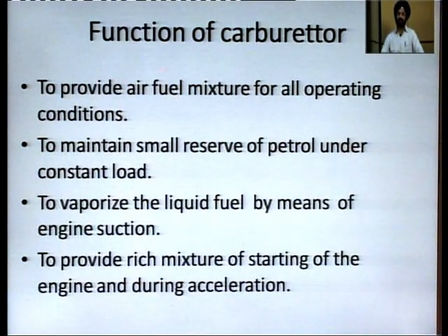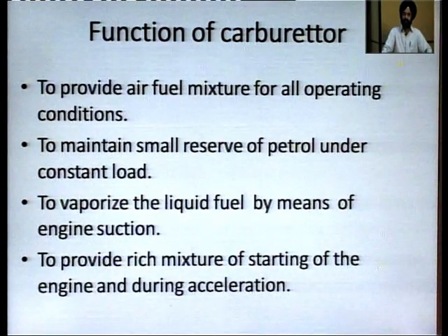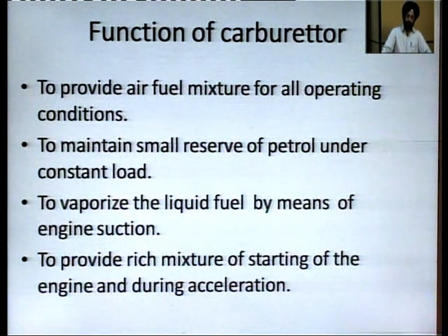So, these are the functions of the carburetor: to provide air fuel mixture for all operating conditions as we have discussed earlier, to maintain a small reserve of petrol under constant head, to vaporize the liquid fuel by means of the engine, and to provide a rich mixture for starting, power and during acceleration. So, these are the main functions of our carburetor.